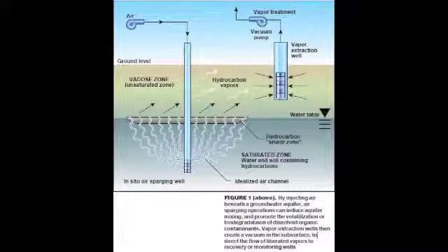Air sparging involves delivering oxygen below the water table to stimulate aerobic biodegradation of contaminated groundwater using the indigenous microbes. It has been successful in restoring polluted groundwater aquifers. The cost can be less than $1 per 1,000 liters. It is definitely the cheapest bioremediation method.